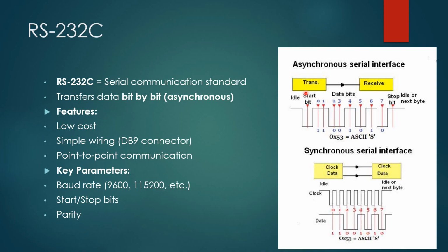So, by the way, the start bit indicates the transmitter is transmitting data, and the receiver will collect the information, where 8-bit data are available here. And once it sees the stop bit, it stops the transmission, and it freezes the data as 0 to 7.